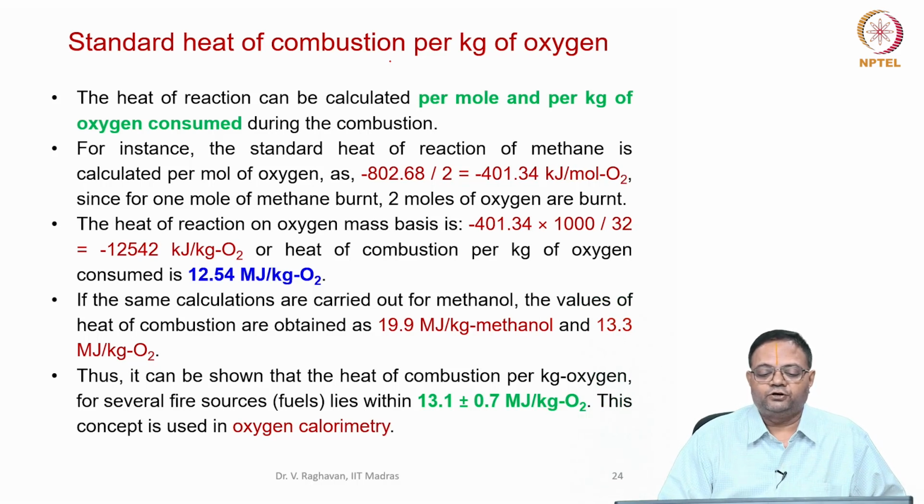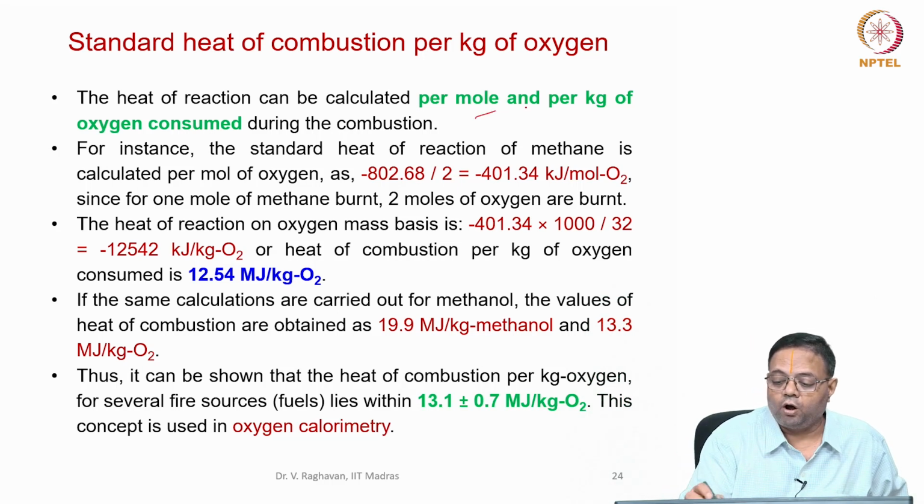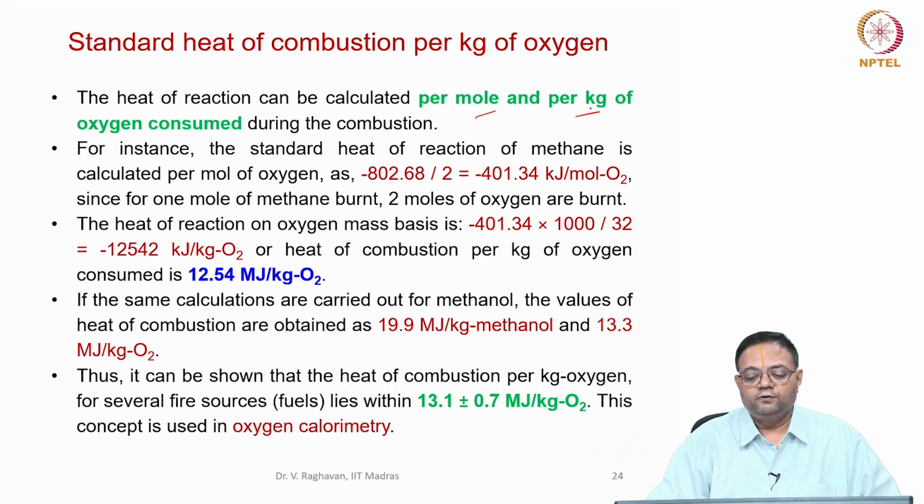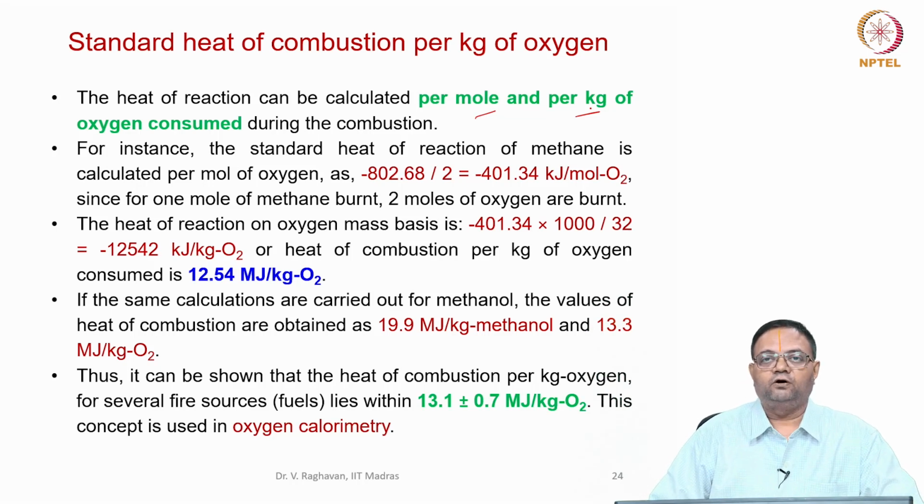Now, heat of reaction can also be written in terms of per mole or per kg of oxygen consumed. This is very important. So, let us take the instance of methane combustion, where for 1 mole of methane, 2 moles of oxygen are consumed.